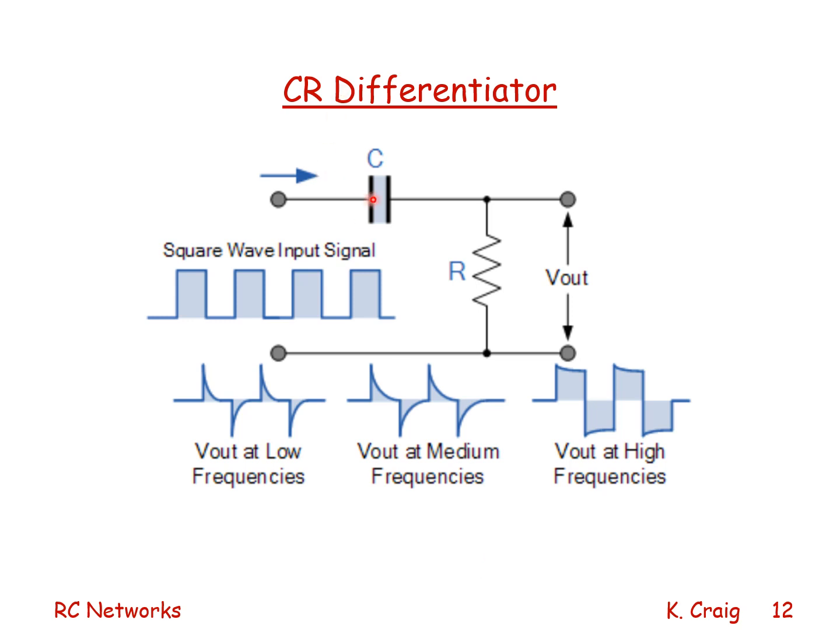Here I have my CR circuit, and the CR circuit behaves as a differentiator for frequencies 1/10 of the bandwidth and below.